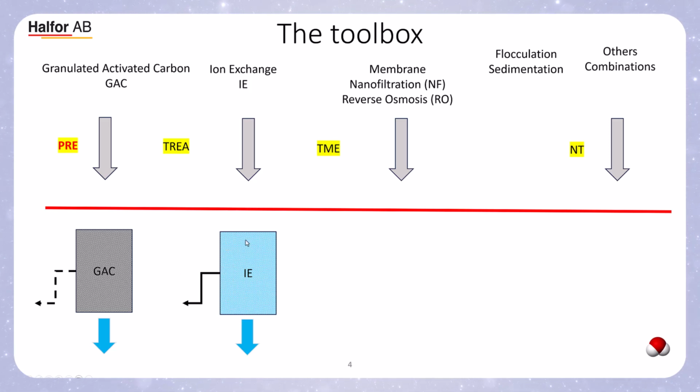Something you also need to be considering is the waste stream that you will get from the ion exchange when you recharge it. That means pushing out the adsorbed PFAS with either chloride or sodium, depending on if it's a positive or negatively charged PFAS you are wanting to remove. So here you will have a waste stream that you always need to consider on how to handle. And in my experience, getting clean water is most of the time not really the problem. It is how to handle the waste stream from the different process steps that you need to work with in order to get the clean water.